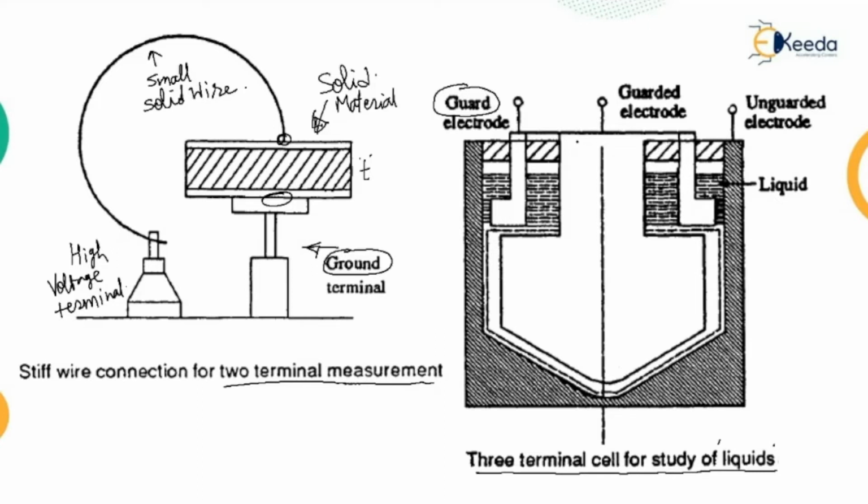The opposing surfaces of the measuring electrode should be carefully finished to give a polished surface and a uniform spacing of about 0.25 mm. That spacing must be maintained. The insulation should be able to maintain the alignment of the electrode even at the highest temperatures used, and should still allow easy disassembling and cleaning.